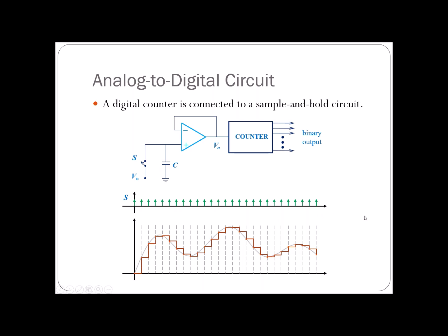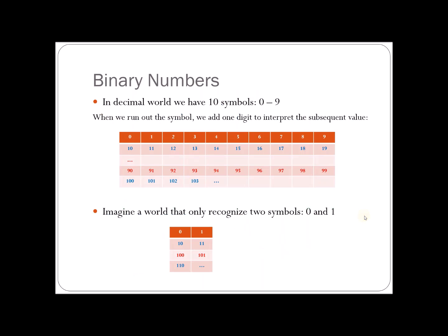So as we have already mentioned at the beginning, the discretization in this digital signal is not only happening on the time axis, but also in the y-axis there. So how to digitalize it? Well, this is pretty straightforward. The signal in the y-axis will only be recorded at the closest value, the discretization of the y value.